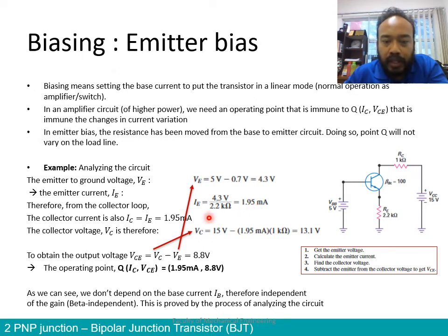Therefore, if you want to find the collector voltage VC, what is VC? VC is basically the voltage between the collector point C and the ground. So for example, it is the voltage in this particular loop over here, if I may draw to help you. VC is this voltage over here, VE was this here. So VC is the voltage when you compare this point and the ground. If you put your voltmeter, this is what we call VC.